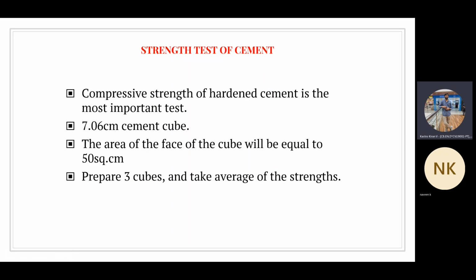And the next test is the strength test of cement. In this test, what we are going to do is prepare a cement cube with a dimension of 7.06 centimeters.